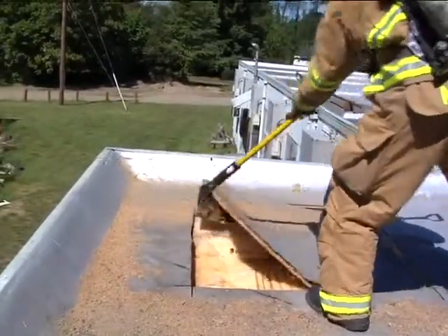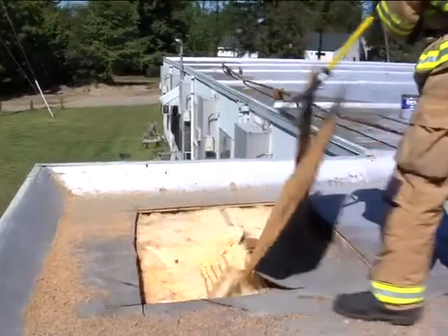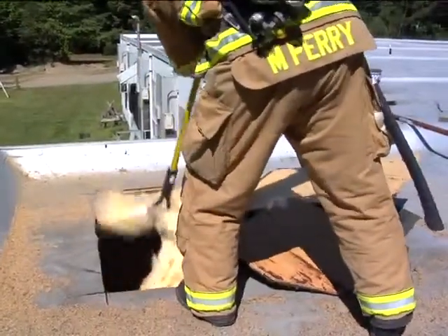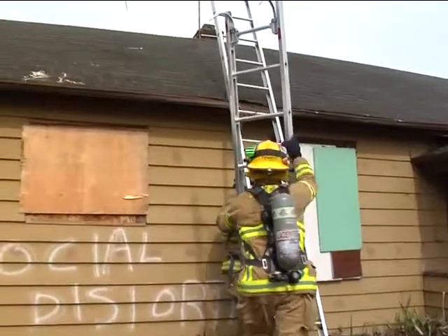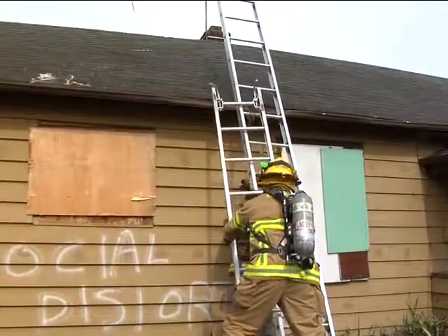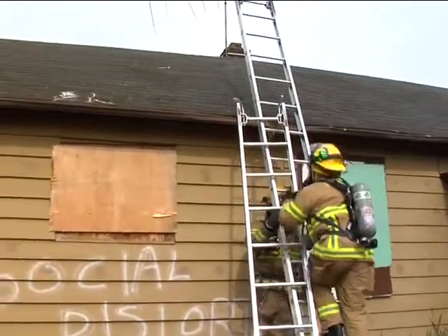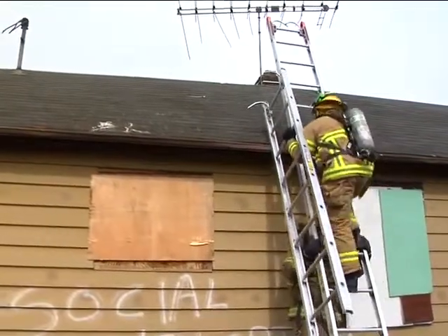Use a hand tool to pull the cut section of the roof decking out. Push through the hole to open the ceiling. The procedures for opening a pitched roof with hand tools are similar to those for flat roofs, but the incline requires you to take additional precautions to keep from slipping off.